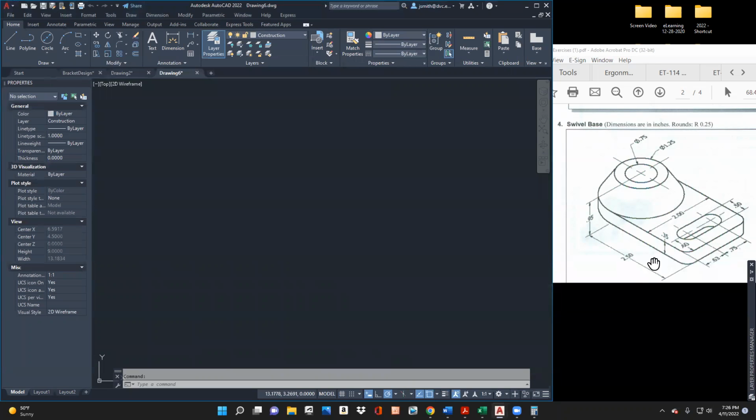Now, this part is a little deceiving, because if you add up 0.63, 0.75, and 0.63, you actually get 2.01. So it should actually be 0.625. They round it up, which is probably not the smartest thing because it's very confusing and you get some weird numbers. So we're just going to round this down to 0.625, and that gives us 2 inches.